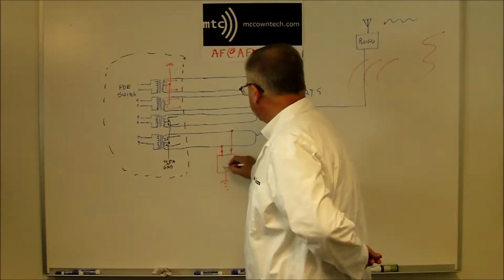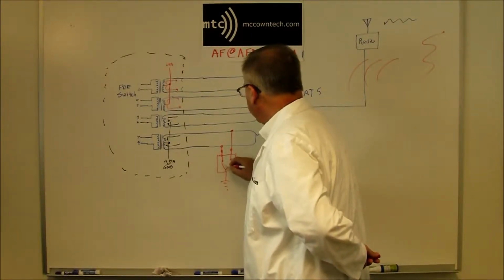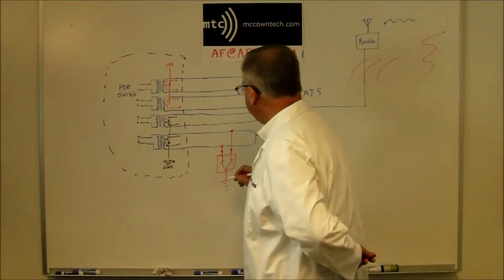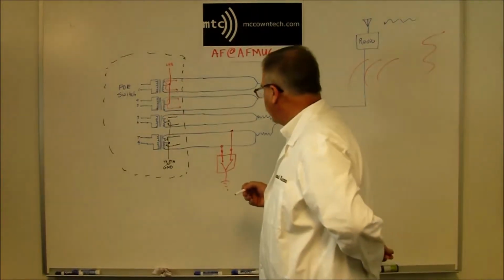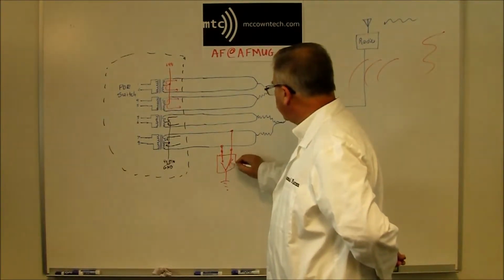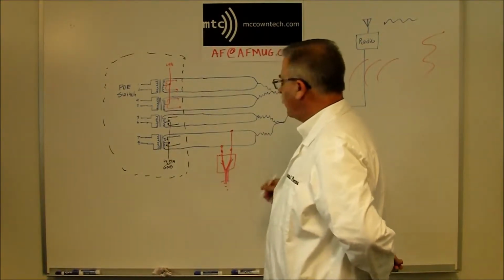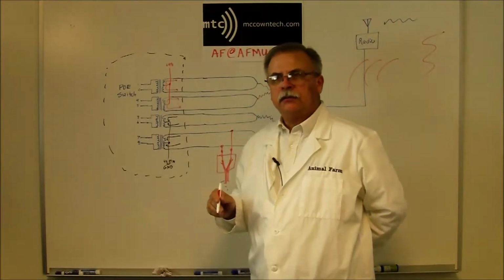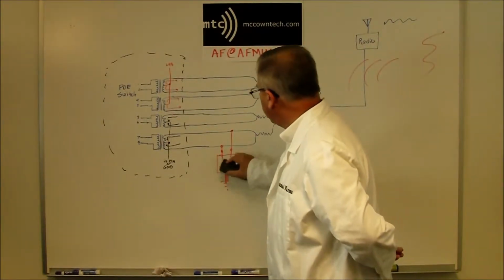basically it's just a switch. It's a solid state device. Well, in my case, my products have both a solid state and a gas tube device. I don't even know what that would be called, a gas state. It's not a vacuum tube. When it sees a high impulse, it just shorts things to ground and bleeds off all of that juice until the surge goes away, and then it opens back up and waits for the next impulse.